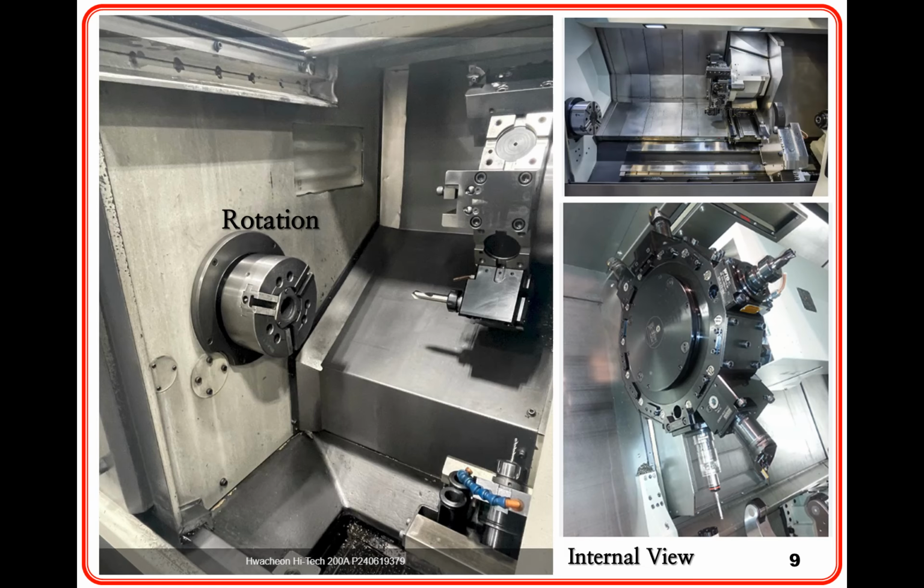The part that rotates is the headstock. The headstock transmits the rotation of the spindle motor to the chuck, mounted at the front of the spindle, through belts and transmission gears. The picture at the bottom right shows the tool turret. Depending on its design, a tool turret may be classified as a drum-type turret, a disc-type turret, or a horizontal-type turret. Multiple cutting tools can be mounted on the turret at the same time, allowing the machine to automatically select and change the tools required for each machining operation.